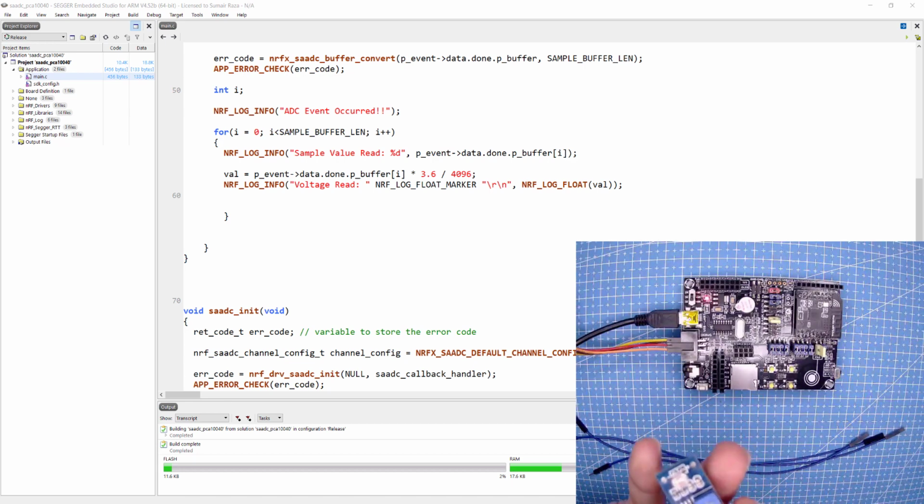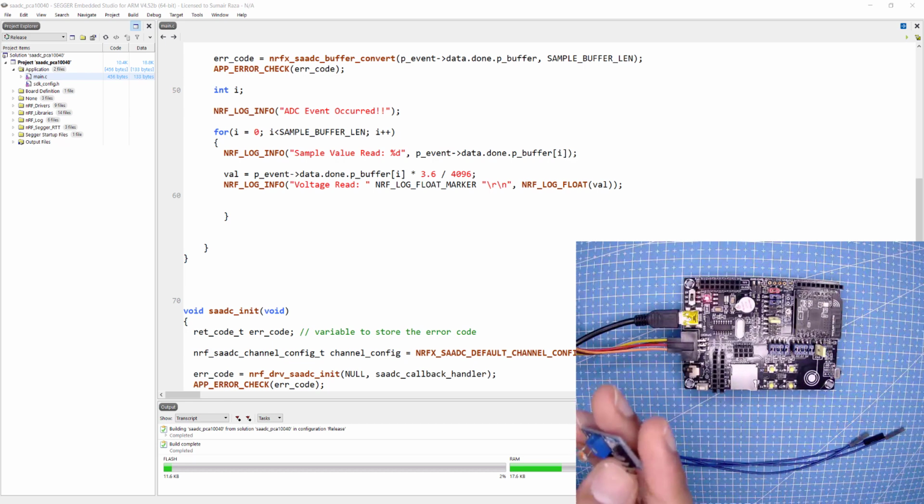This is a light dependent resistor module, and basically it's connected with a comparator and with some variable resistor, so we can change the resistance, and it's going to give a single output. So we have two pins here, one is D0 and one is A0. A0 is for analog and D is for digital.